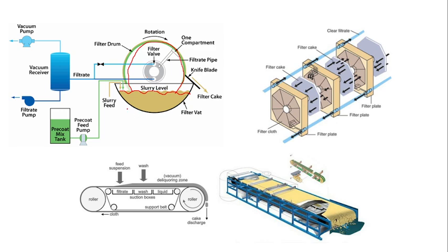Okay, when we are passing the slurry, this filter drum is constantly rotating in this direction. All the slurry liquid will be passing through the filtration setup and the clear water will be separated, and all the retentate matter, whatever substances are not passing through the filter matrix, will settle upon this drum and be eliminated in the form of filter cake here.